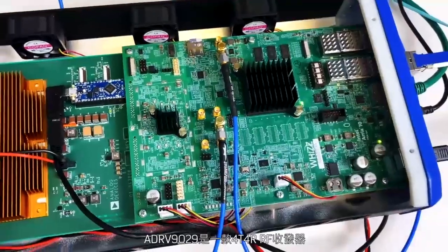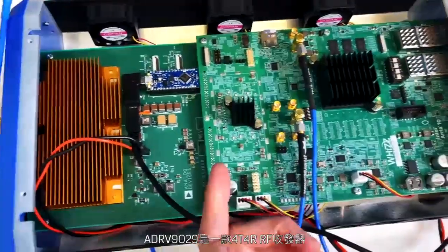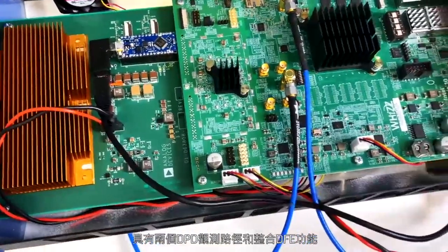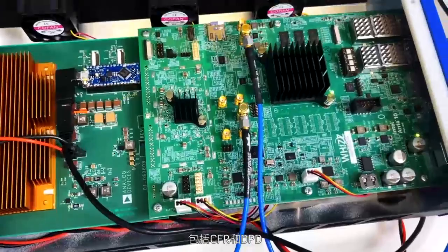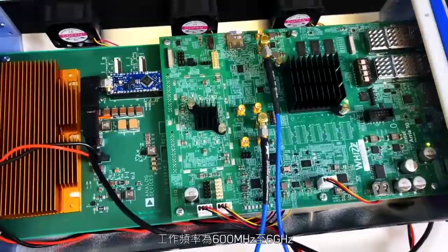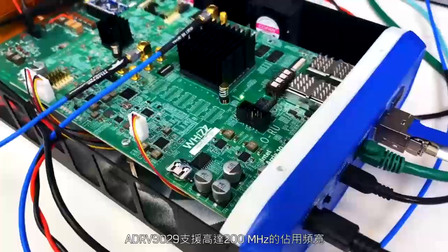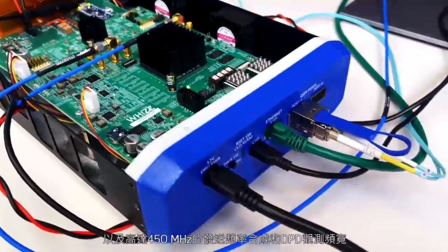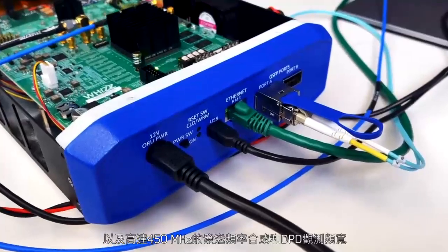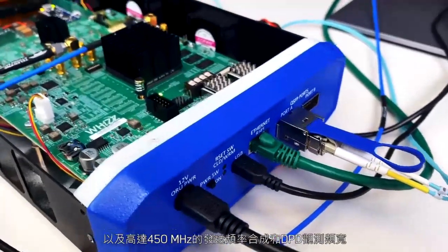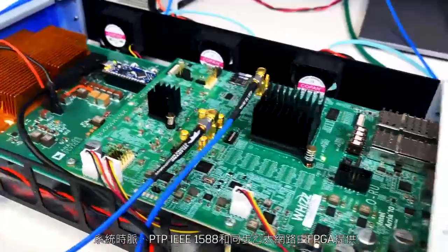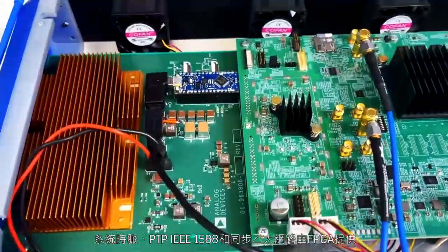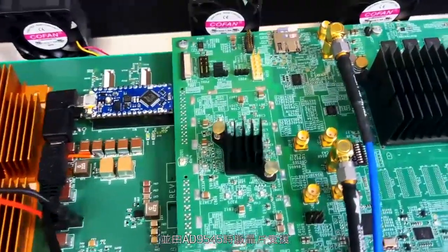The ADRV9029 is a 4T4R RF transceiver with two observation paths and integrated DFE functions including CFR and DPD, operating from 600 MHz to 6 GHz. The ADRV9029 supports occupied bandwidths up to 200 MHz and transmit synthesis and observation bandwidths up to 450 MHz for DPD operation. System clocking, PTP, IEEE 1588, and synchronous Ethernet are provided by the FPGA and supported by the